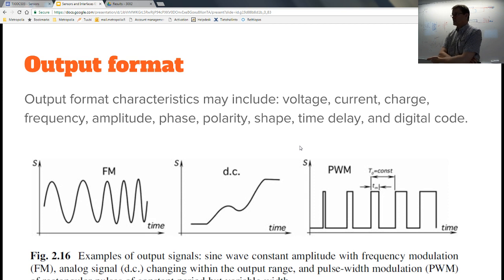There is a 4 to 20 milliamp standardized signal there. Then there's another standard which is 0 to 20 milliamps, which means basically that the sensor should give values linearly related on that range. The span of the sensor is fixed with the span of that output.